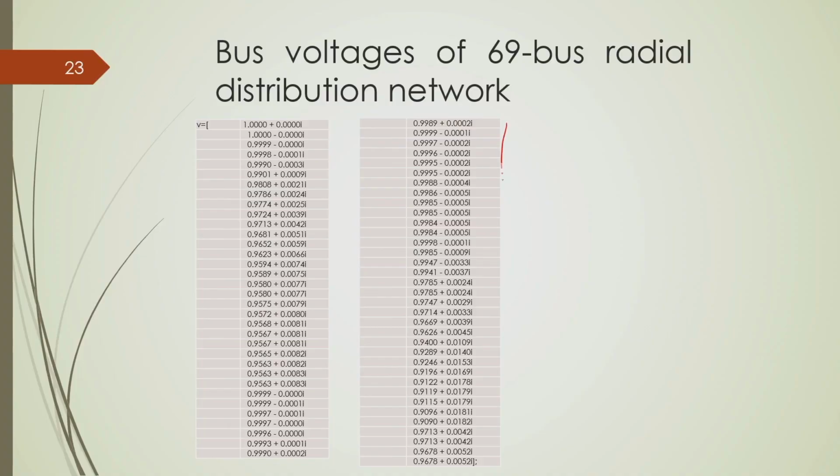Okay. Now, these are the values of these bus voltages in per unit or load voltages in per unit. So, this is the complex voltage which gives you the voltage as well as the angle. So, if you take the absolute value of this, it will give you the voltage magnitude. If you take the angle of this, it will give you the voltage angle.